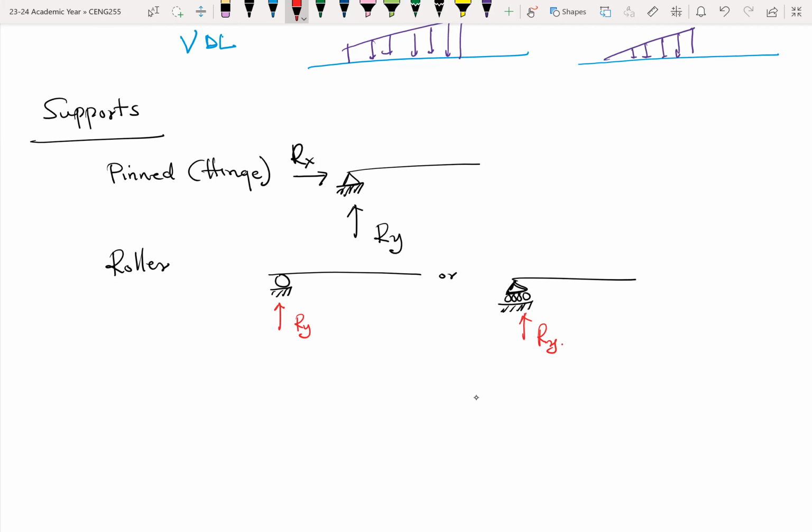Okay. And we apply this a lot in bridge design. Normally for bridges, they're usually made up of steel structures, and steel structures tend to expand, or they respond to temperature changes. All right, significant responses, so thermal changes, which means that when the weather is very hot, the bridge will expand. When the weather is cold or cooler, the bridge materials will contract.